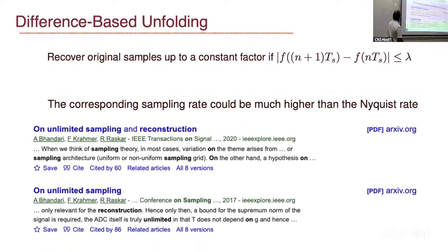So these are the first few papers that talked about this kind of reconstruction, but several such reconstructions existed much earlier in different contexts. I talked about oversampling, right? Oversampling means how much above the Nyquist rate. The first few papers talked about an oversampling rate of 17 times the Nyquist rate. They say that for band limited signals, if you sample at this rate, you are guaranteed that you can reconstruct the signal from folded versions. We'll get back to your question, why should we do oversampling, later. But the oversampling rate was this much.